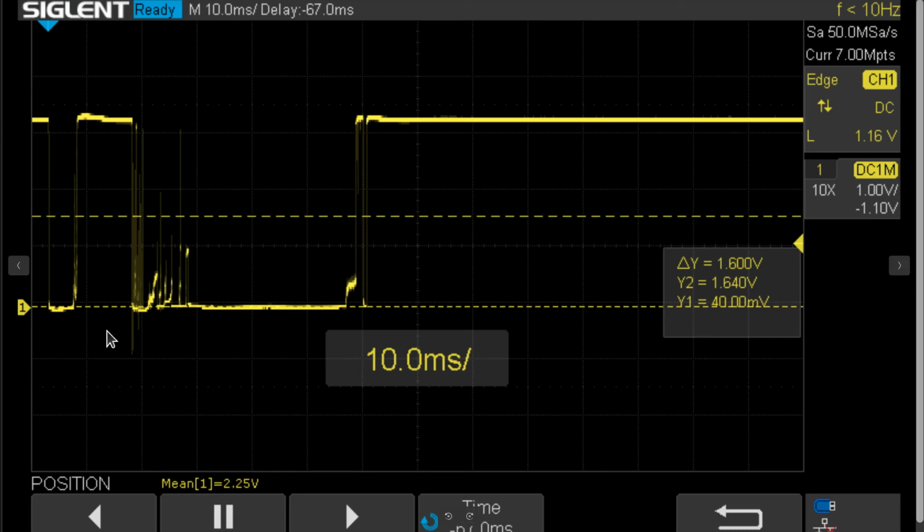Okay, if you tune all this right, you'll see that no matter what we do, this can always happen, and this gap can always be bigger than whatever you've tuned it to. You can't do this perfectly. It just can't be done, right? Because a switch is a mechanical thing, and people's hands quiver and move, and they bounce, literally physically bounce, or they don't press it right, or they're grinding it and rocking it back and forth, and a little bit of a glitch might sneak its way through, and it might be longer than whatever you set the time to.